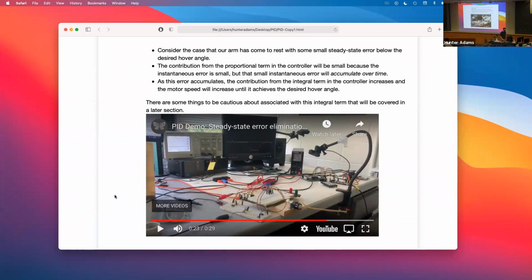Will that be like the faster you snap, is that proportional gain instead? Yeah. So this ends up being combating forces here. The higher you turn up the proportional gain, the faster the response. But the faster the response, the greater the potential overshoot and the longer the ringing. So you're trying to balance speed with overshoot and settling time.